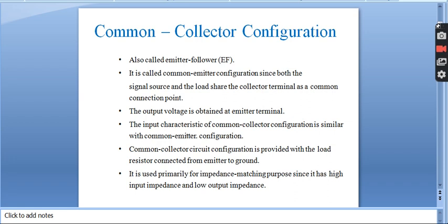In this common collector circuit configuration, a load resistor is connected from emitter to ground instead of being connected across the collector. It is used primarily for impedance matching purposes, since it has high input impedance and low output impedance.